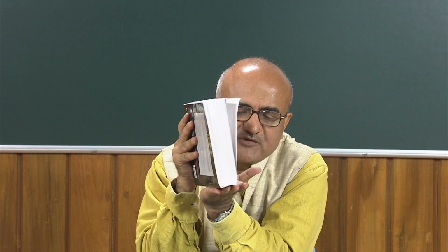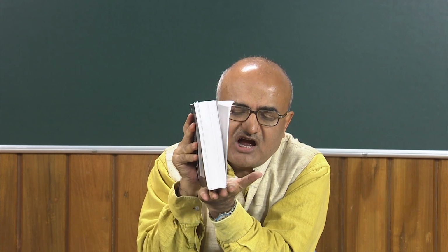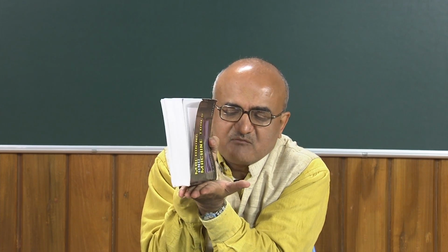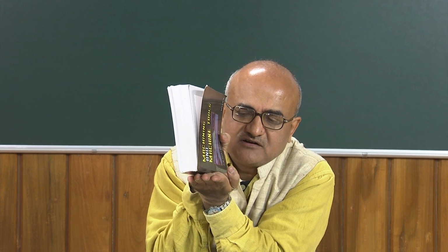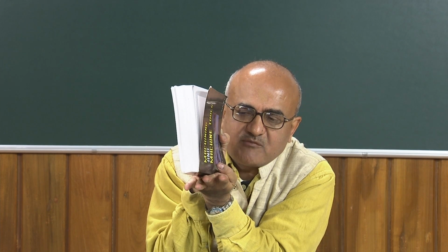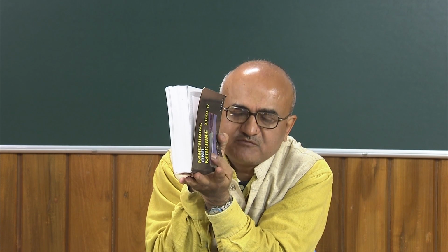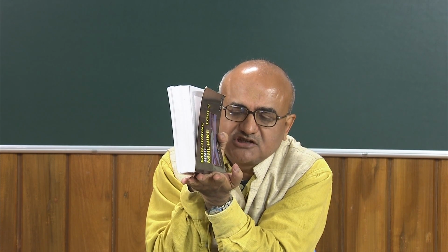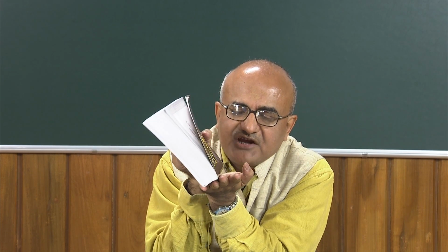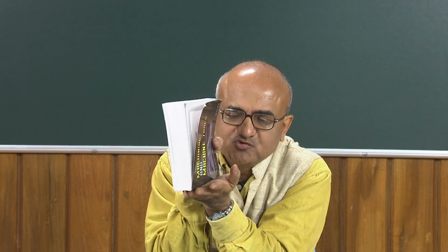Okay. Now what happens is that this one is cutting like this. Suppose I cut. Of course, if I move this book on my palm, then some portion of the material ahead will come out in the form of the chip, and it will slide on the vertical surface. That means the chip will be moving on the rake surface. It may have some resistance, so it is better to incline it towards this side, that means the positive rake angle side, so that the chip can easily move.